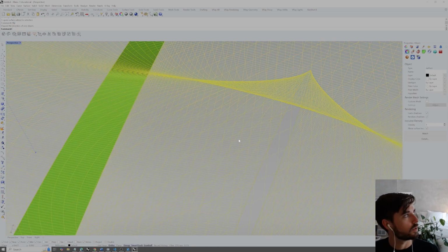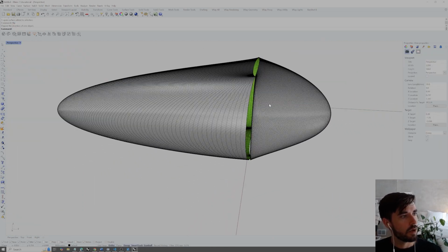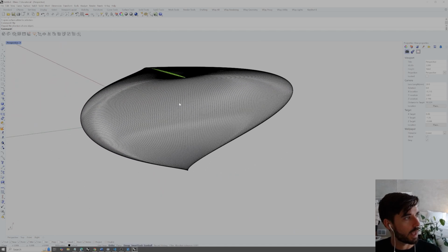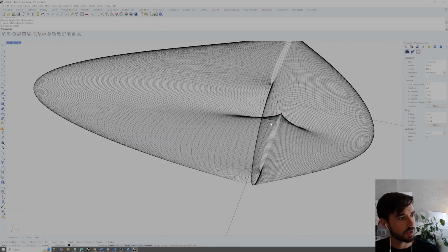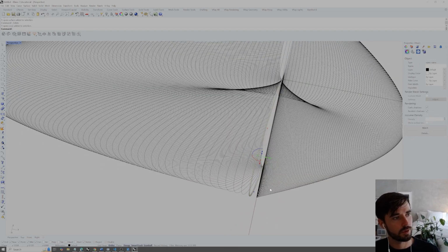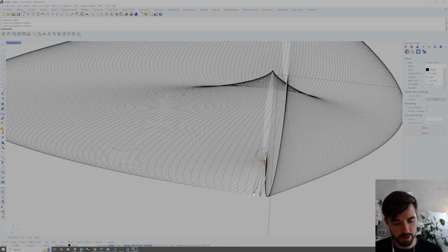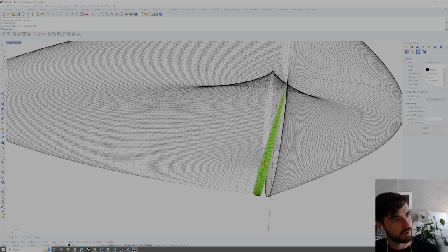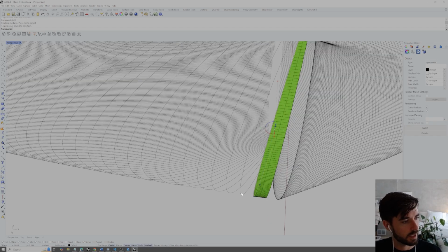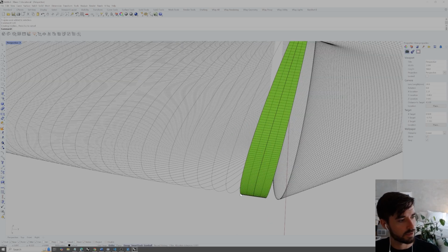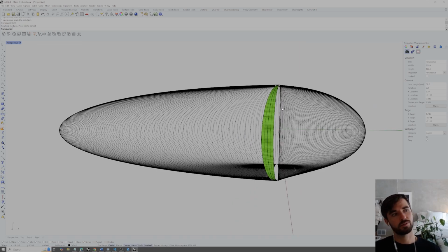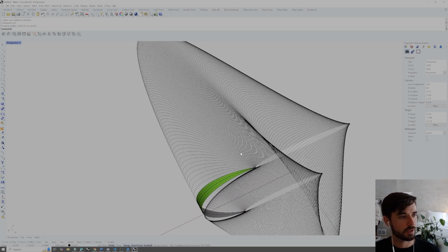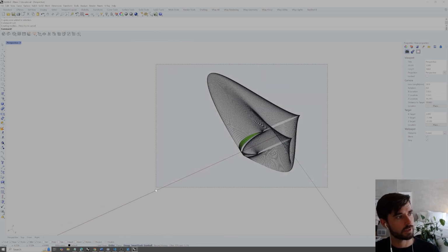And what it's able to do is read in all of those curves, and then between each curve, loft each one together. So essentially it's just automating the process of selecting these two curves, typing loft, hitting enter, selecting the next set, typing loft, hitting enter, and going all the way through these. We can only do this because we've structured our curves based on u and v values to make these parametrized surfaces.